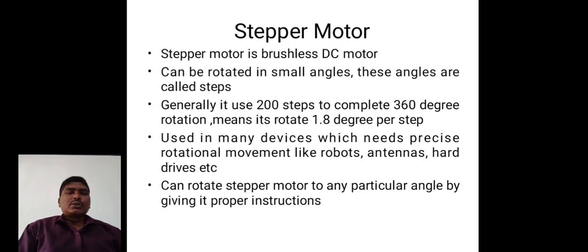If you divide 360 degrees by 200, you will get a 1.8-degree step. So it can rotate the stepper motor to any particular angle by giving it proper instructions.